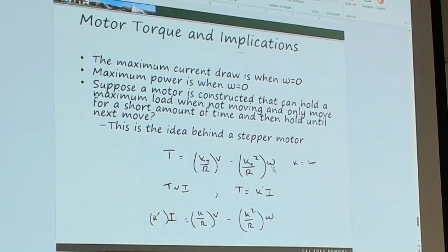Remember I told you, if your motor is a 6 amp motor, your power supply shall be 6 amps or greater. Your driver shall be 6 amps or greater. Why? Because of that condition right there. That's our start condition. So we have start and stall. At stall, we burn up our motor. But we have to have enough power into our motor from a current source to overcome that initial torque. That's really all these equations are saying right here.